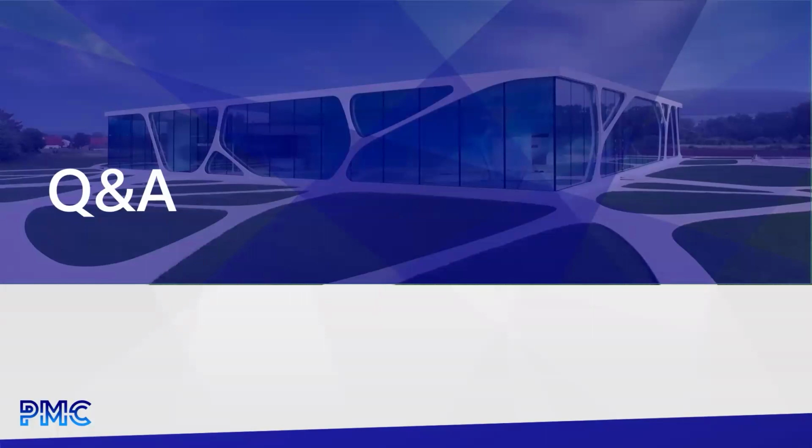Another question we had, can you help us geolocate a point cloud when you complete a scan? Oftentimes, we have clients who own multiple buildings on a campus who will eventually want their buildings to be virtually connected by location and elevation. Yes, this is something we do all the time. With the survey, we can put this building into the correct coordinate system, whether it's state plane or whatever they're working on. We can get that information and capture it.